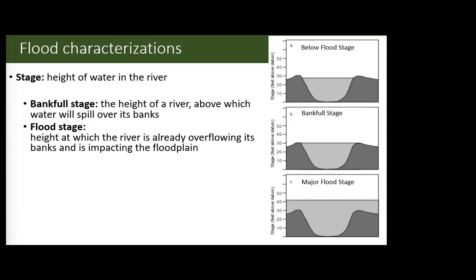And then flood stage, that's the height at which water is overflowing out of the sides of the channel. With each channel, you can see these slight slopes on the exact sides of the channel. Those are known as natural levees because as you get those flood deposits, it builds up silts and clays on the sides. That kind of helps to dam it up. But that's where we measure our bank full stage from, the tops of those natural levees on the sides. Anything that goes over that is going to be at a flood stage.